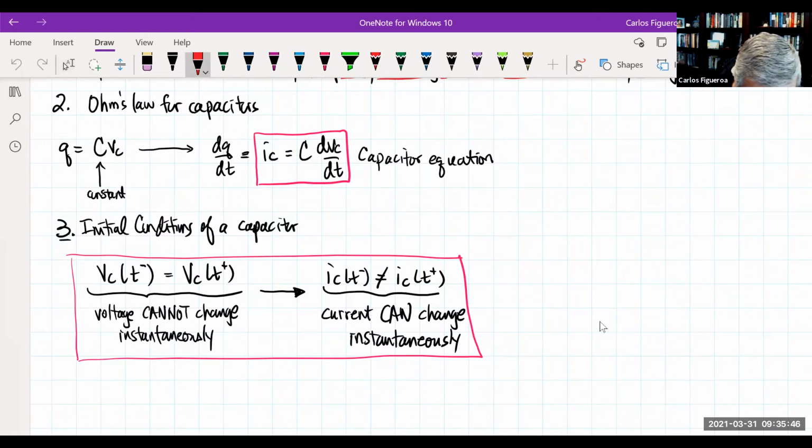What it says here is that the voltage of the capacitor can't change instantaneously. And what that really says, and you may have learned this in your 4B class, is that capacitance is almost like an inertial type property for charge. You can't get rid of charge very quickly on a capacitor, so there's this lag time. You could say that capacitance is like the inertia, and because of that, the voltage can't change.